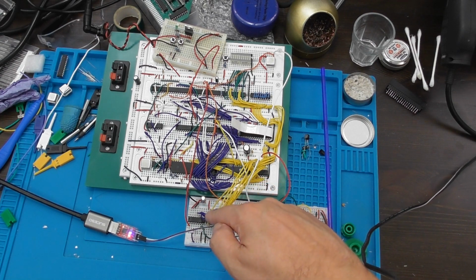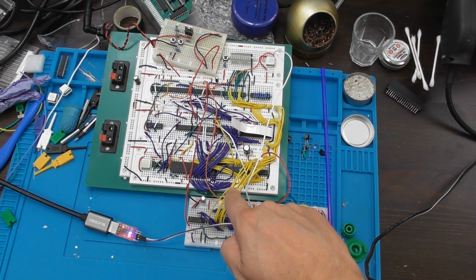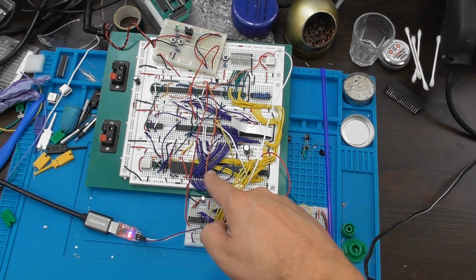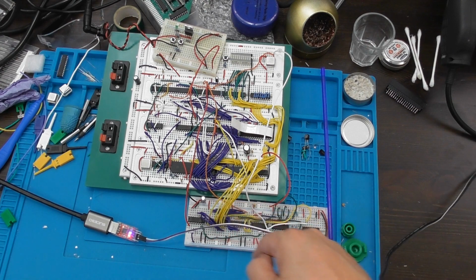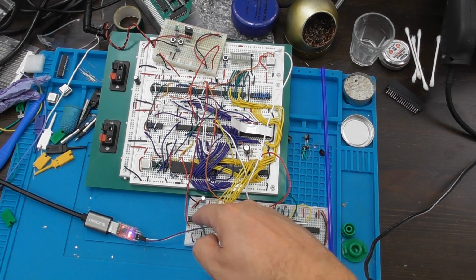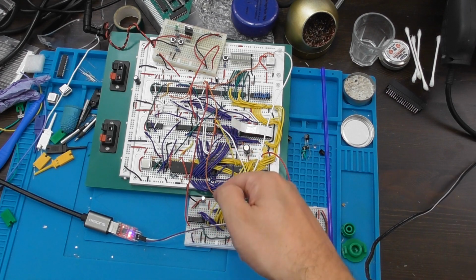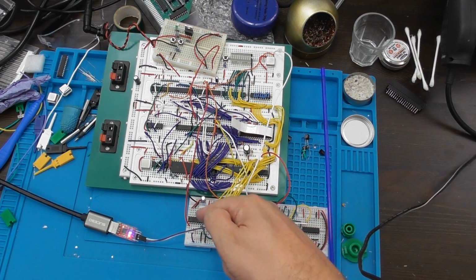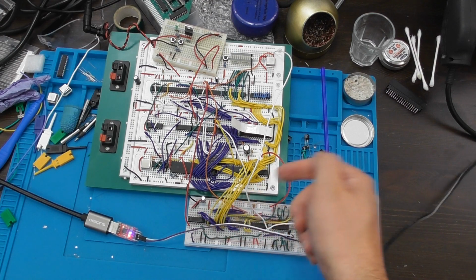It presents itself as a transmit data port. It's connected to the data bus, so when the CPU writes a byte of data to that address, it transmits that character. And there's also a readable register which informs the computer when the device is busy, so that the computer can wait until it's not busy before sending the next character.